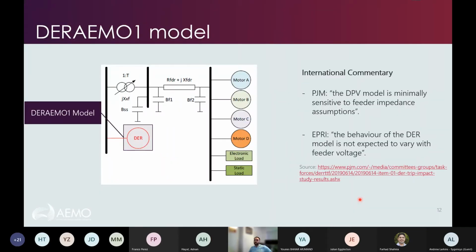So the latest approach recommended by NERC and the WECC is to split the model between utility DER and residential DER, plugging in the utility DER here and then your residential DER at the load bus. When AEMO started modeling the composite load and DER models, the idea was still in draft stage. So we modeled it at the transmission network, had a lot of feedback from NSPs saying, is that right? Should we be modeling it that way? And our preliminary findings have shown that it doesn't make a big impact because it is an aggregate model.